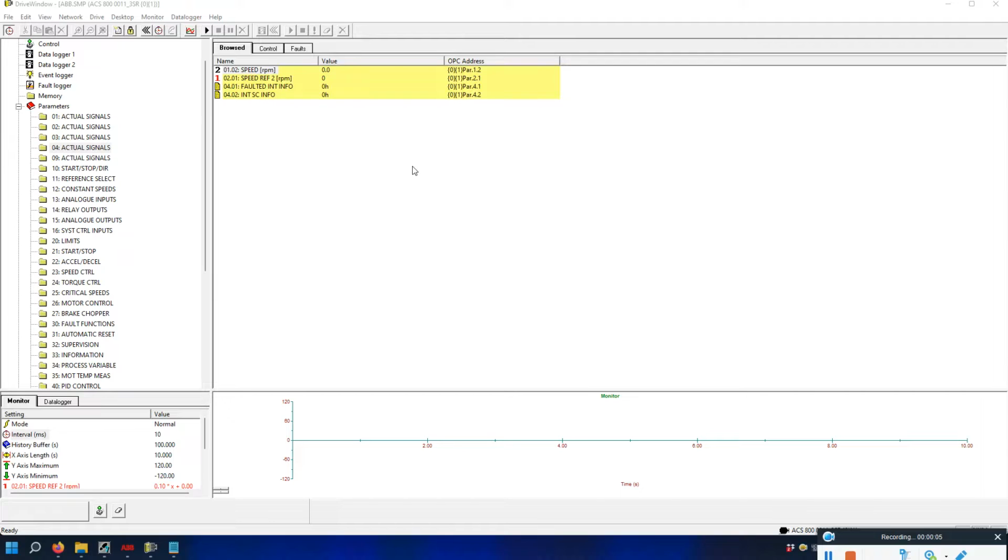So today we will be explaining how we can communicate and start the drive ACS800 drive from Siemens S7 PLC. So this video will be a continuation from my before video. I did a video about ACS800 basic commissioning, so this video will be a continuation from that. Okay. So let's first configure this drive for the profibus connectivity.